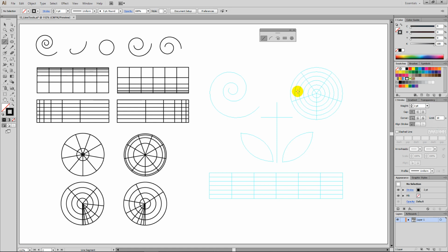On the first page, I will show you how to draw the basic line drawings. Select the Line Segment tool. Hold down Shift and drag horizontally along the cross guideline to draw a horizontal line. Hold down Shift and drag vertically to draw a vertical line. As you have just seen, holding down Shift and clicking and dragging will allow you to draw horizontal and vertical lines. Clicking and dragging the mouse without pressing Shift will allow you to draw lines at free angles.